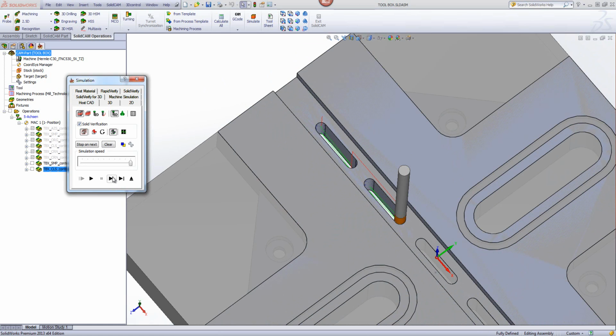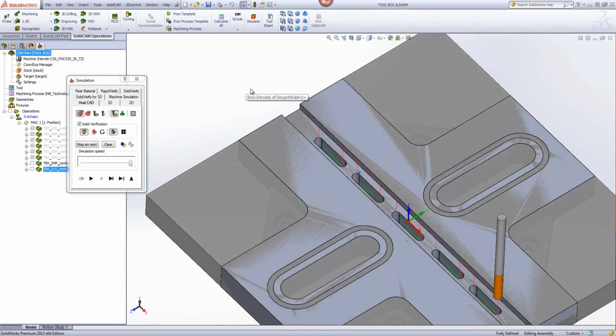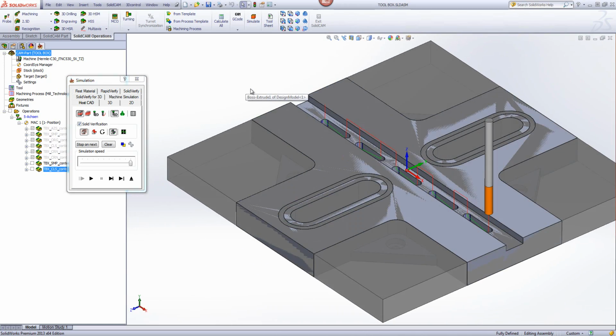And at the very bottom, by the way, when it finishes the very bottom, it actually does one pass that's going very straight at the very bottom to clean up whatever's left over, as it did right now. Same thing over here, going back and forth. Very, very useful operations. Okay, now I've had actually a customer that has very small slots exactly like this.